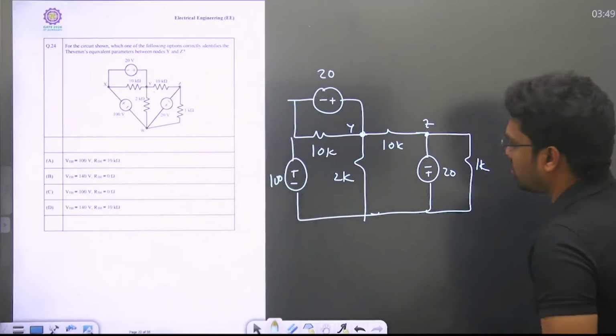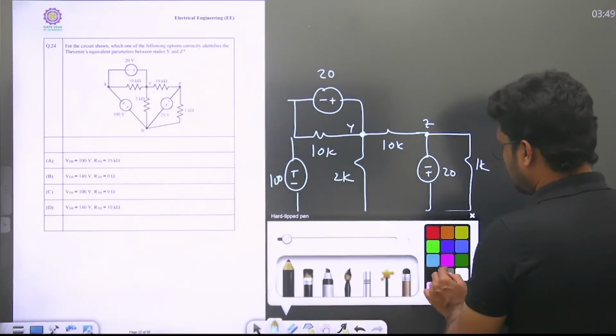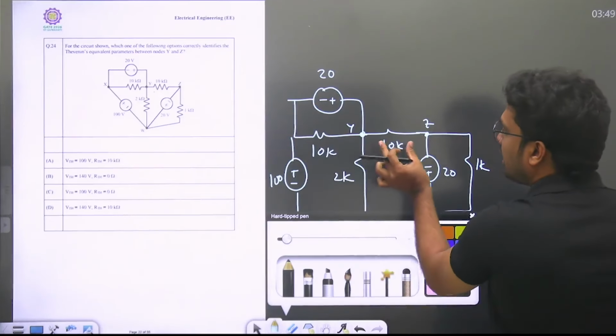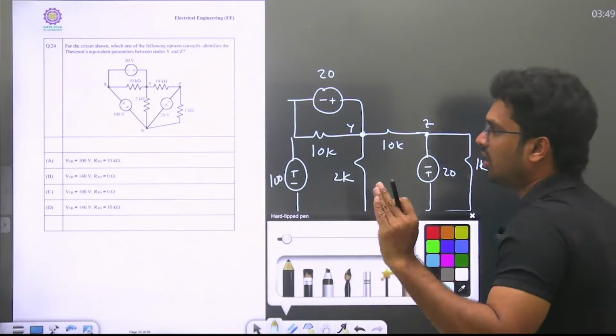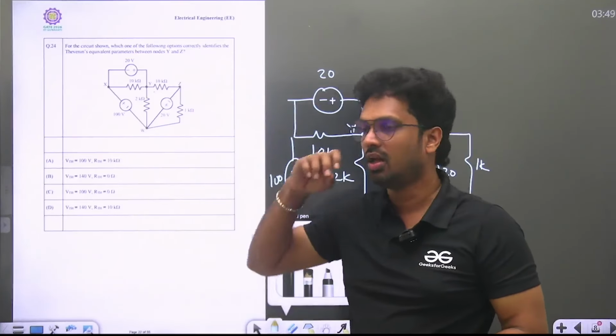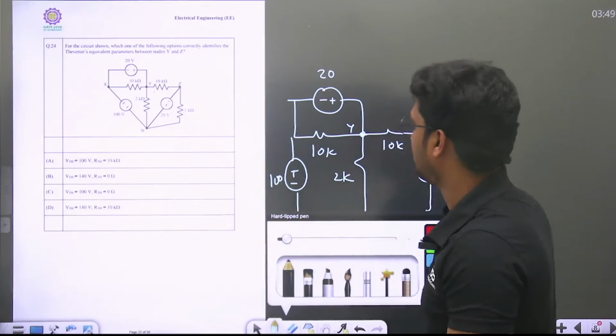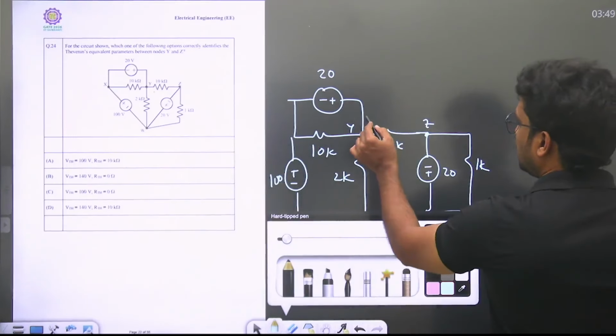So we can open circuit it. In fact, whether you open circuit it or not, in both cases your answer is the same. But as I told you, because the polarities are given, I am assuming the response is required here. If polarities are not given, generally, unless we require a response in this branch, we should not remove it. Okay, so what is VTH?